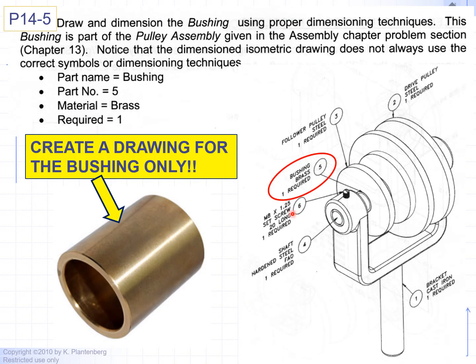Next slide. Okay, here we have a bushing. Just imagine we have this fork made out of iron. So that the hole doesn't get damaged from wear and tear, one of the options you have is to insert a press fit bushing. You just make this diameter slightly larger than the hole, so that way you'll have an interference fit where the hole is smaller than the cylinder, or in this case, the press fit bushing. So you can force it in there, tap it in there, or you can press fit it in there with the machine.